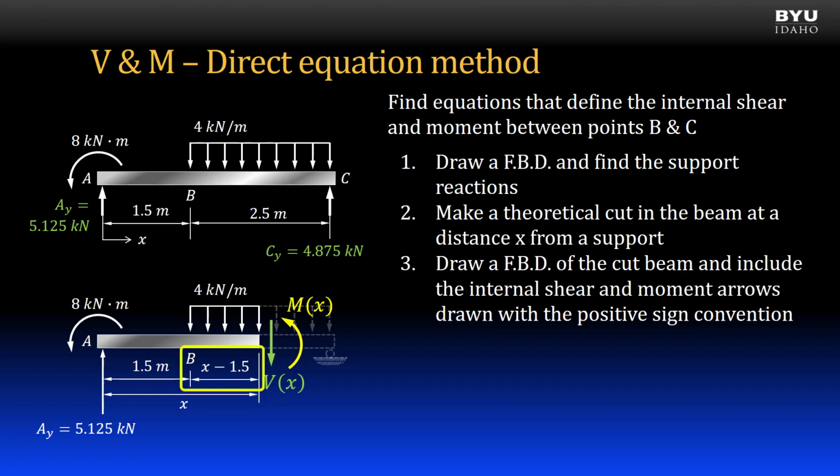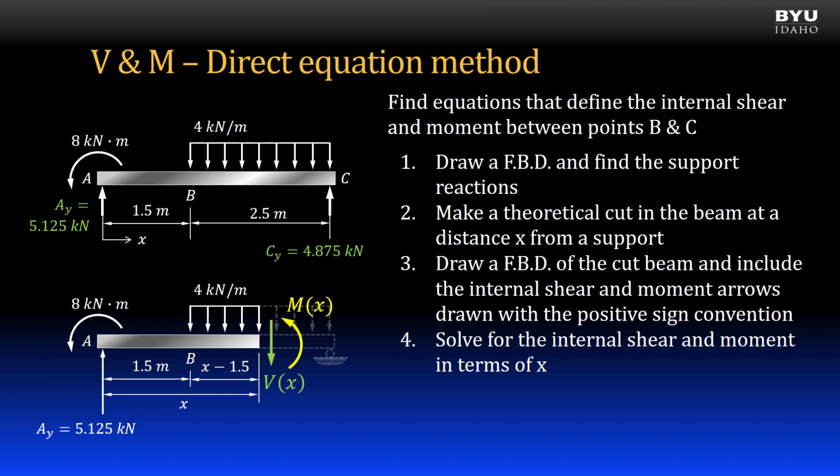It is x minus 1.5 meters. The next step is to solve for the internal shear and moment in terms of x. To find the internal shear, sum forces in the y direction to 0. To find the internal moment, sum moments to 0 about the cut point.